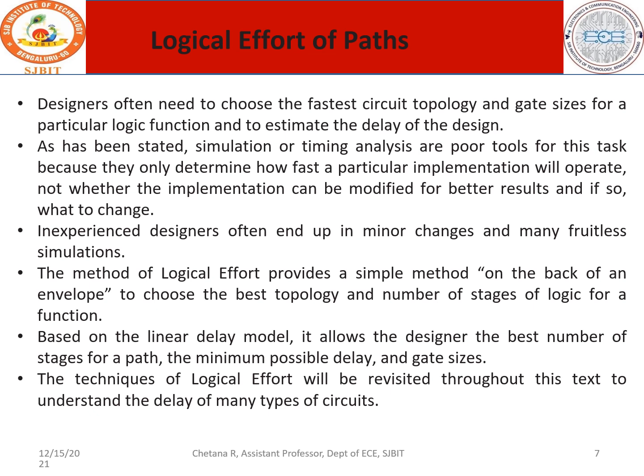Because as the number of stages increases, the delay also increases and speed is reduced. Therefore, that is calculated with the help of logical effort. Based on the linear delay model, it allows the designer to find the best number of stages for a path, the minimum possible delay and gate sizes.